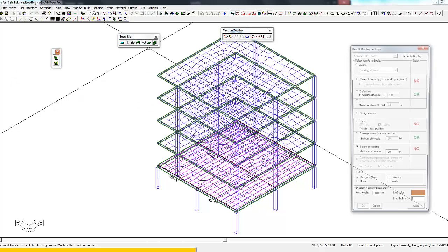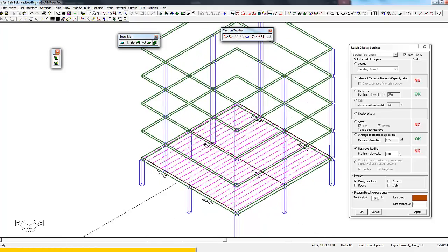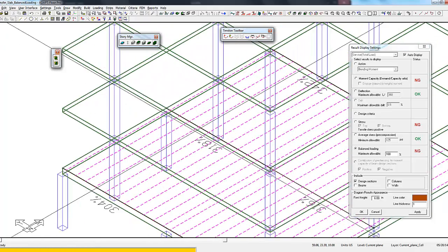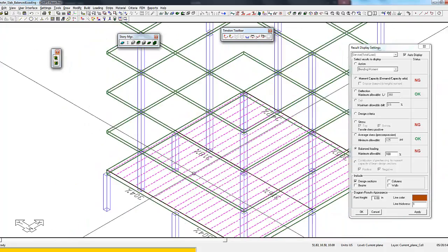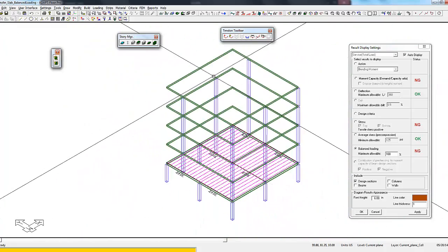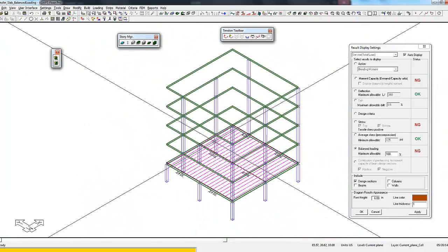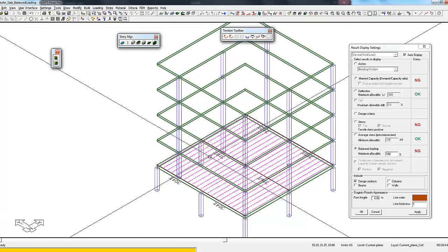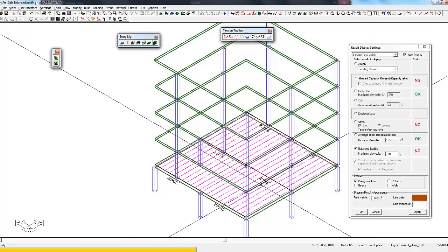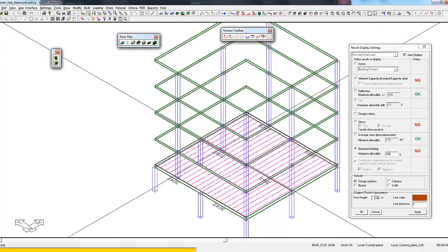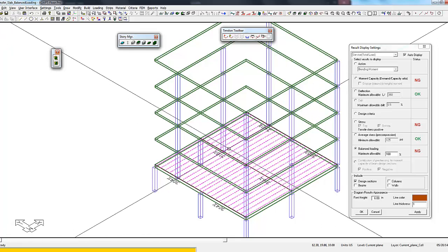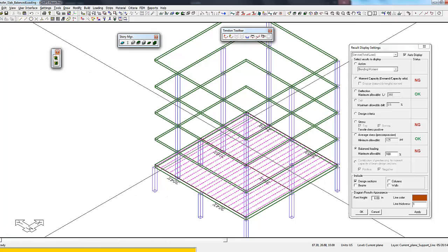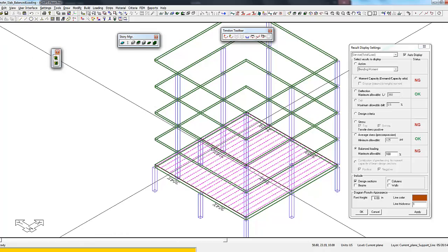we'll turn off the FEM display. Notice that the balance loading percentage is still the same. So the program is not considering these loads in the column that are transferred at this level when it calculates the balance loading. They're considered in the general analysis, and if you were to actually design this strip, you would see a spike there for the moment, but for balance loading it's not considered. So this is still the same percentage.